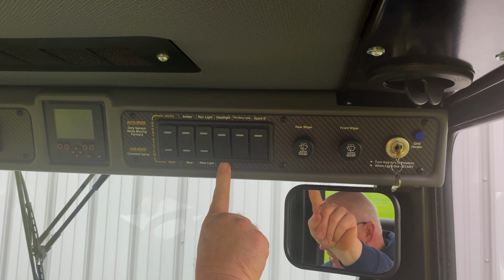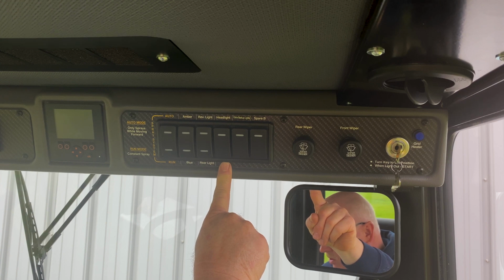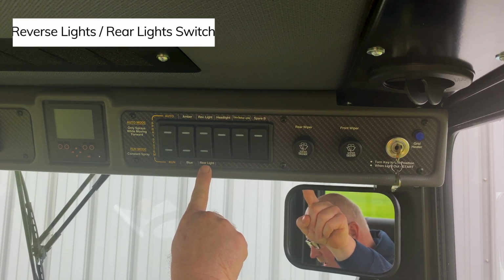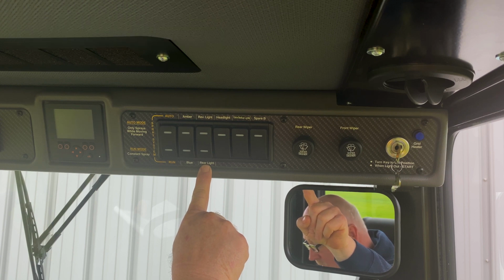Headlight switch. This switch turns the headlights on and the running lights on. The column-mounted turn signal controls the high-low settings for the lights. This is done by just pulling back on the signal lever to adjust from high to low beams. Reverse light and rear light. With this switch, the operator can select the rear light to stay on all the time, or that it comes on only when the tractor is put into reverse gear.